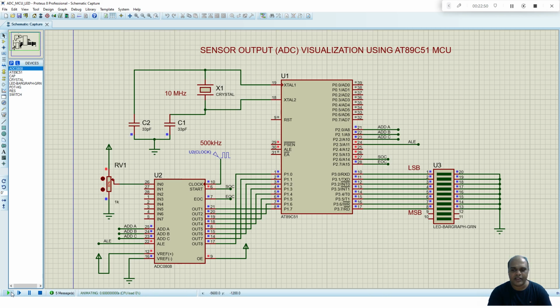When I start executing this, you can see that for this input voltage, 80% of the reference voltage, we get this binary bit pattern: 11001100. If I change this voltage to some 50% or 60%, right now it is 53% of your reference voltage, you can see the corresponding binary bit pattern here, 1 4 zeros 1 1 1.